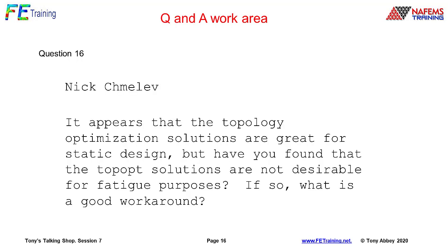Nick says, it appears that topology optimization solutions are great for static designs. Have you found that the optimum topology optimization solutions are not desirable for fatigue purposes? If so, what's a good workaround? This is where there's a lot of work going on. Static design, as evidenced by minimizing compliance, has been typically the starting point, and now we're starting to see dynamic analysis coming in, and quite a few solvers can handle normal modes analysis, for example. I've seen some extensions into fatigue analysis. I haven't really followed them through yet, so I would expect over the next 5-10 years more disciplines are going to be embraced in there.